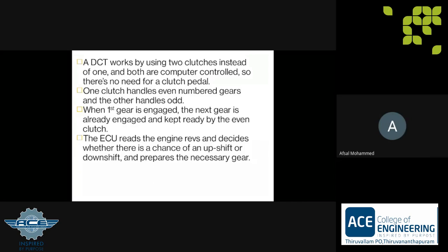However, this can drive up the price insanely high. A Kevlar clutch can cost anywhere from twice to thrice as much as a normal clutch. And also, since there is much more friction involved, the life of the clutch is not as long as the other types of transmission systems. Also, since it is not immersed in oil, there is high friction, and it can also cause premature wear, and it can cause problems with the transmission that the others do not have.